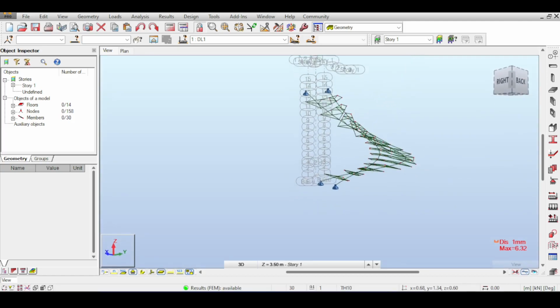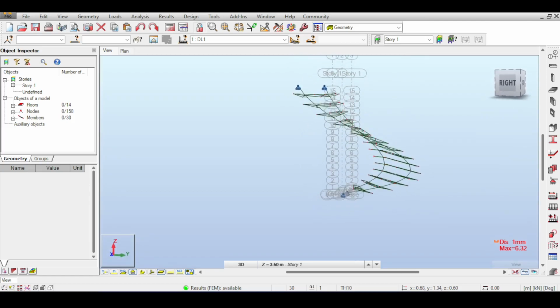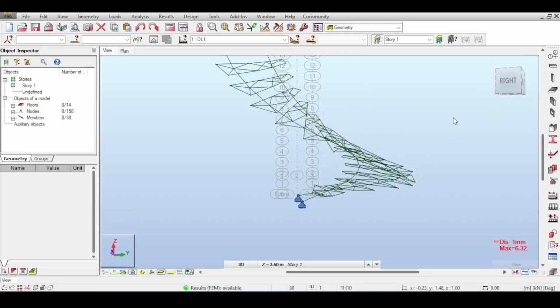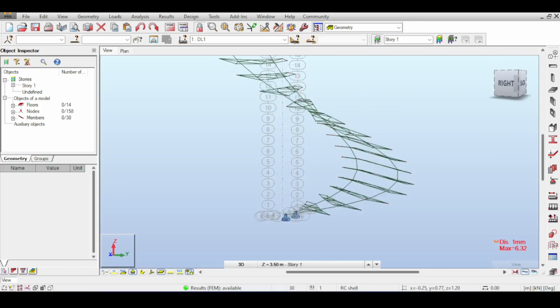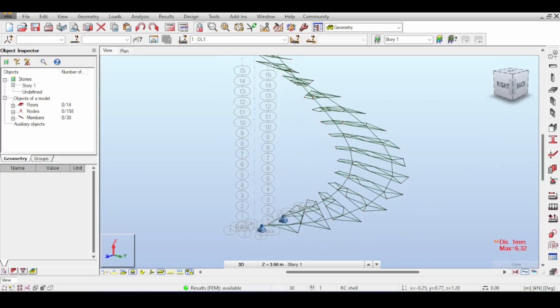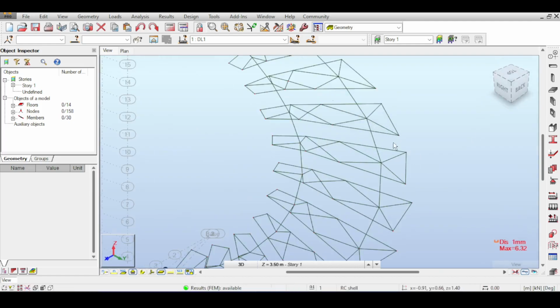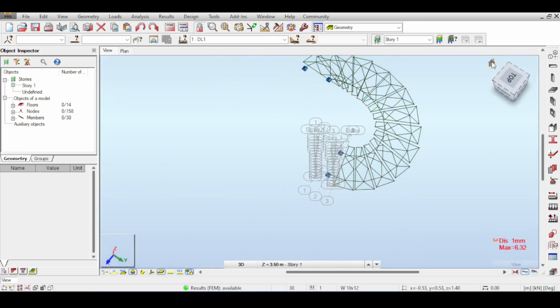You have a higher deflection on the outside and a smaller deflection on the inside because the stiffness of the outside beam is smaller than the stiffness of the inside beam. But why is the stiffness of the outside beam smaller than the inside beam? It's smaller because its length is longer. And also, there is more load on the outside because, as you can see, the staircase is larger on the outside than on the inside. So yeah, everything seems to be working as expected.